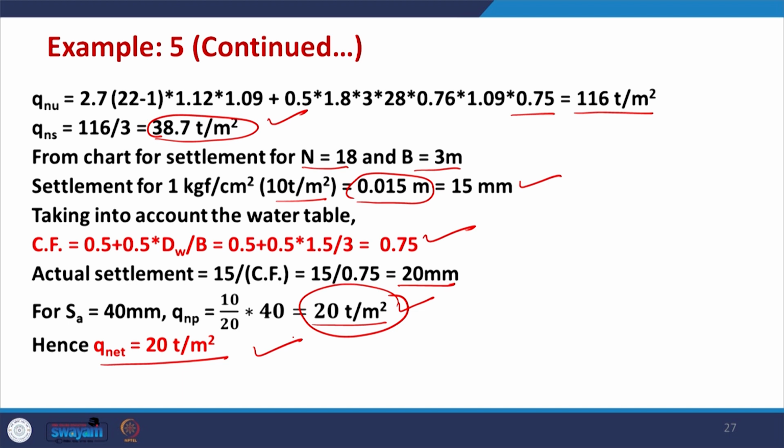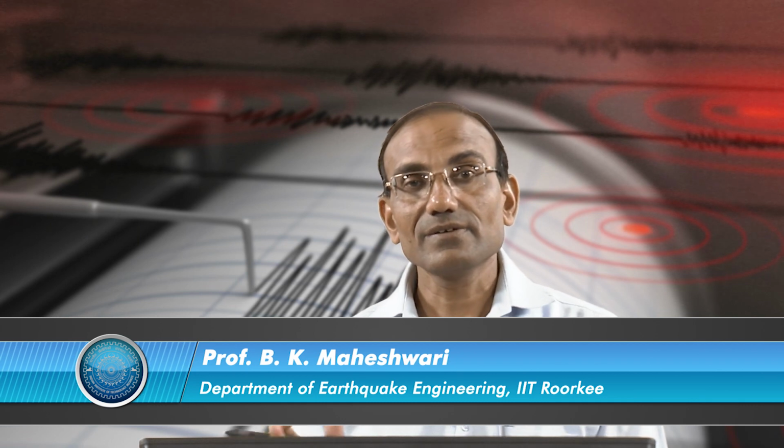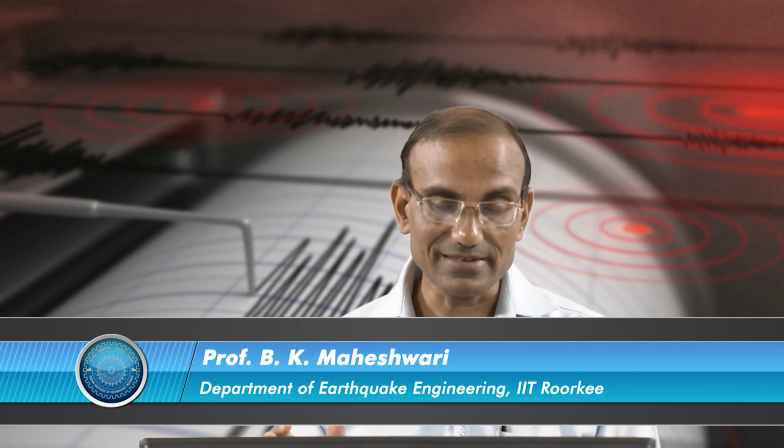So, this was an example using SPT data, and we have done it using both criteria, the bearing capacity criteria as well as the settlement criteria, whichever is the lower value will govern the design, and the answer comes out as the net allowable intensity of 20 ton per meter square.